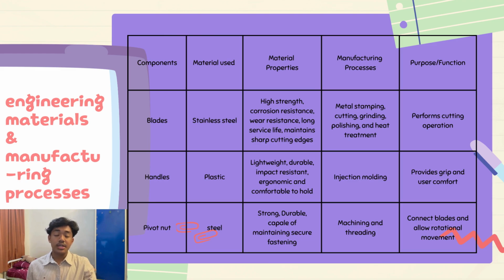So what is its purpose? It is to perform cutting operation. And for the handles, they are made out of plastic and are lightweight, durable, impact resistant, ergonomic and also comfortable for the user to hold. For the manufacturing process, injection molding is used, and the function of it is to provide grip and also user comfort.